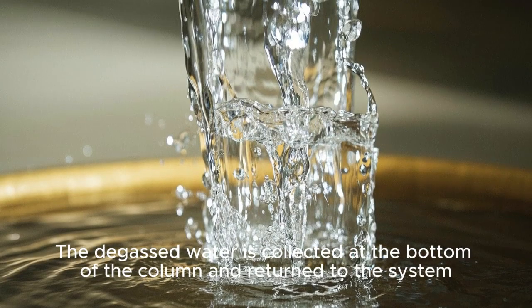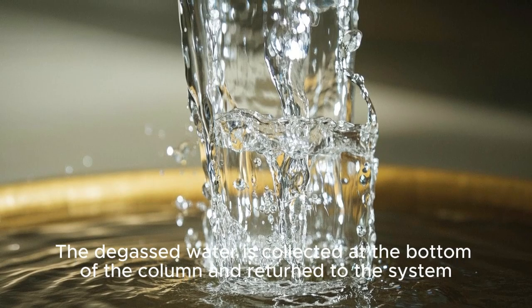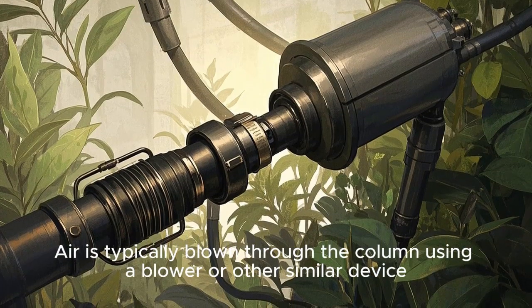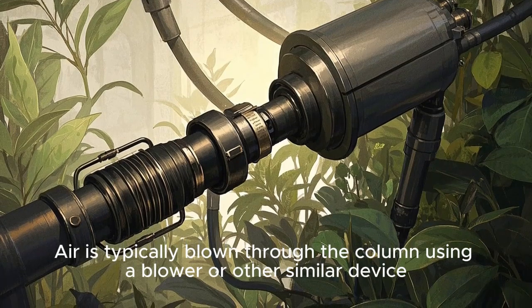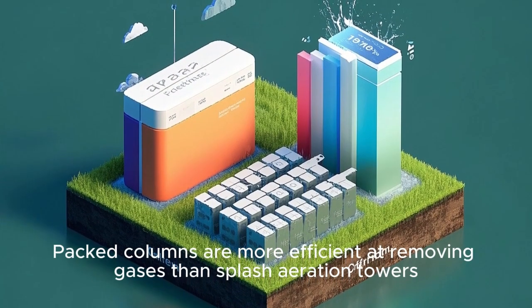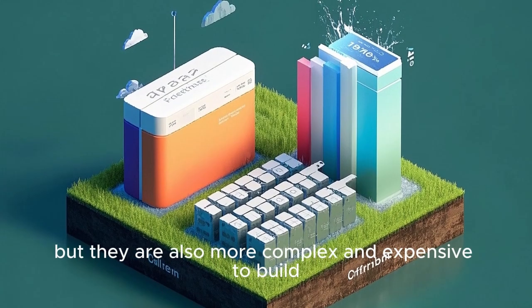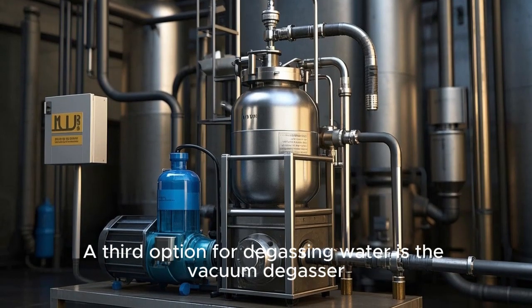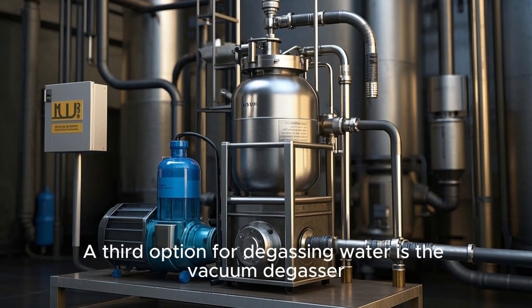The degassed water is collected at the bottom of the column and returned to the system. Air is typically blown through the column using a blower or other similar device. Packed columns are more efficient at removing gases than splash aeration towers, but they are also more complex and expensive to build. A third option for degassing water is the vacuum degasser.